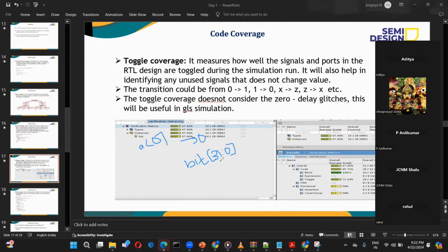In that we can write a reason that only the lower bits are not used. We can understand from the design why these bits are not covered. So based on that, we can think that these lower bits are not covered. So you can directly include that 16 down to 0 as lower bits if we are not using it. Or there could be something like, if it is an aligned address, modulus 4 of 0, whatever is there, those only will be covered, others will not be covered.